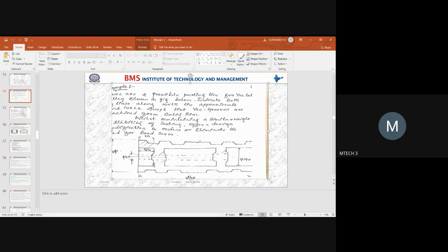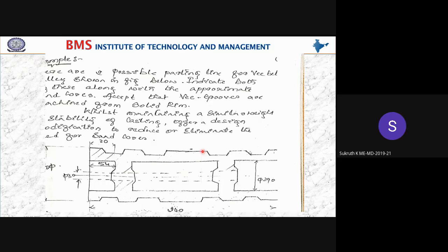So you are talking about this cavity and the center hole. Yes, sir. This cavity. Am I right? So the cavity what we are having here, exactly at this point, and exactly at the center, we require a sand core. Yes, that is one parting line. So any other parting line? There are two possible parting lines, he says.